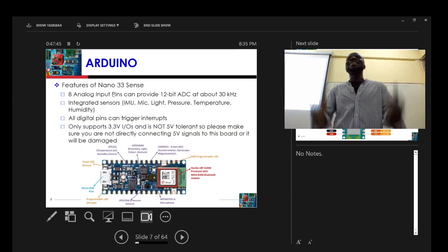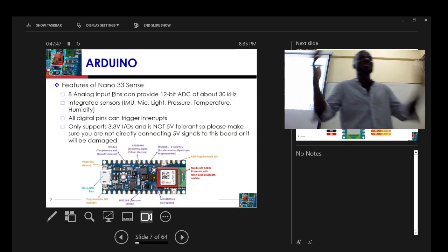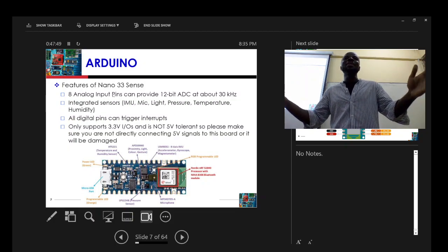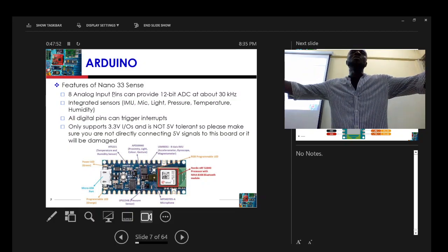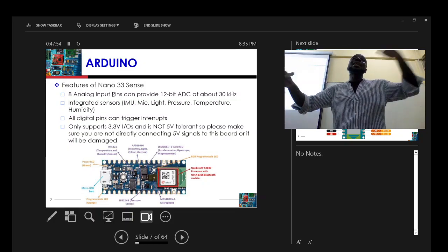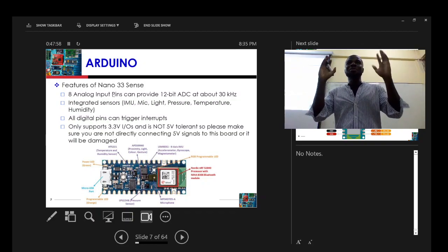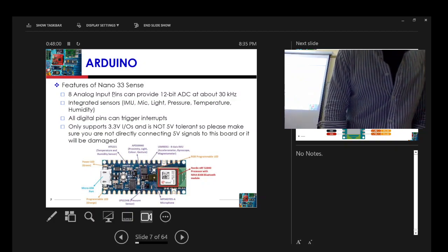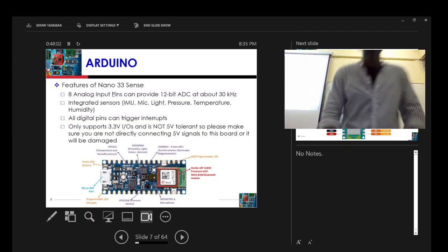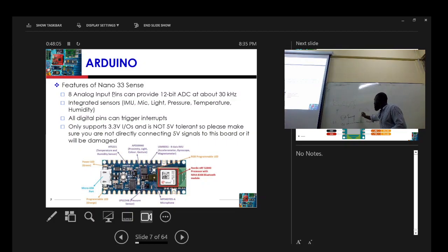As I said, it's a digital pin, and I just took my time to explain it. The digital pins only take 3.3 volts or 0 volts. It can't take half. It's not an analog pin. So how do I do that? Yeah, so that's what we do. We use pulse width modulation.